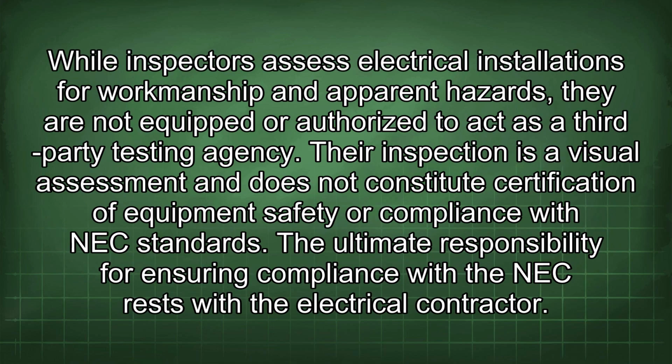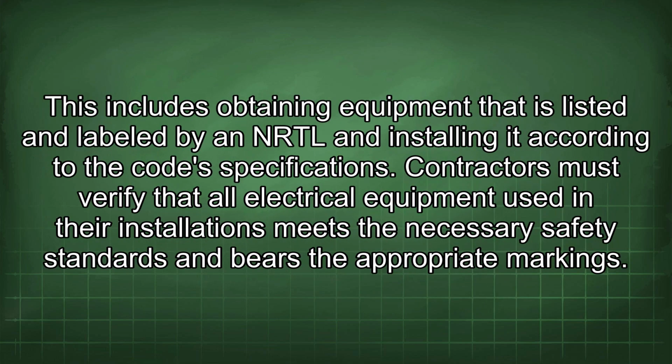While inspectors assess electrical installations for workmanship and apparent hazards, they are not equipped or authorized to act as a third-party testing agency. Their inspection is a visual assessment and does not constitute certification of equipment safety or compliance with NEC standards. The ultimate responsibility for ensuring compliance with the NEC rests with the electrical contractor. This includes obtaining equipment that is listed and labeled by an NRTL and installing it according to the code specifications.